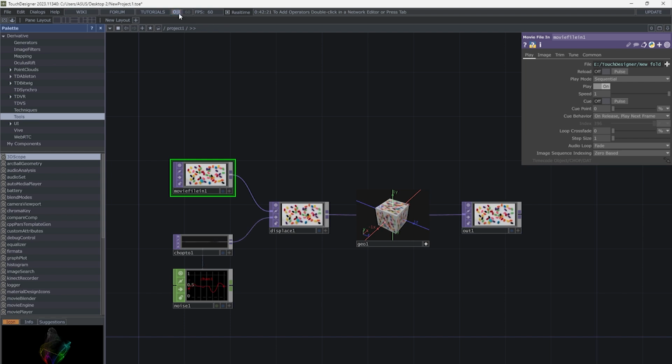This button turns off cooking and completely stops the network and timeline. And this shows your FPS. You need to have a look at it and optimize your work. With real-time enabled, TouchDesigner might decide to repeat frames if the hardware cannot keep up with the selected FPS. This text shows your last work in the network with the exact time.